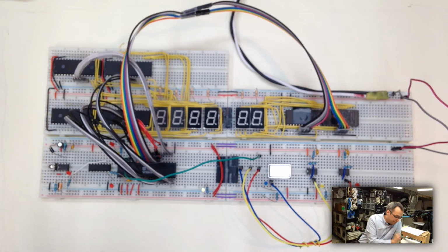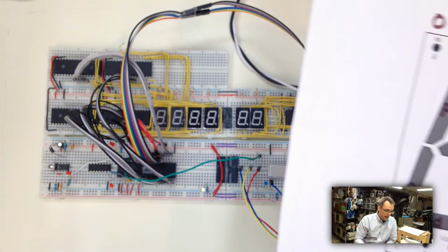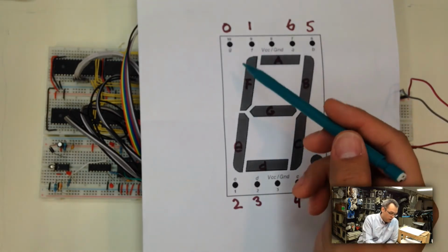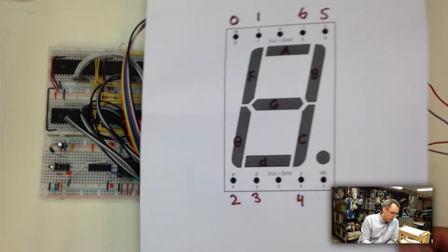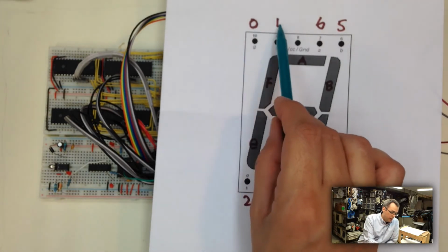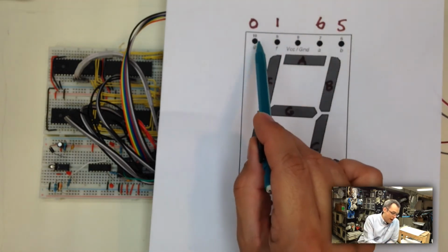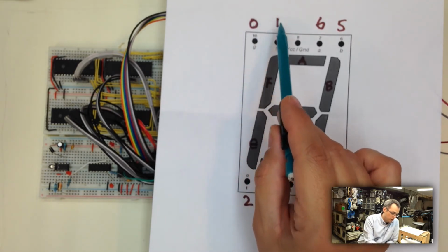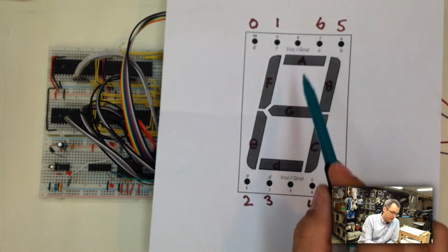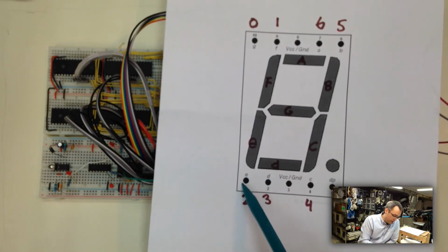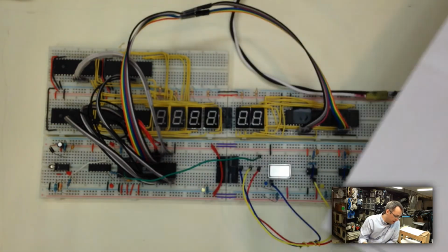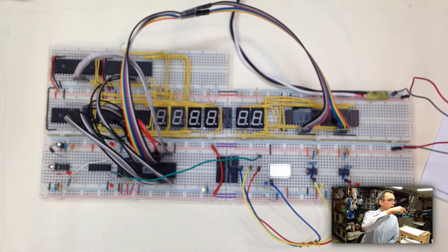And basically what I did, to get this working, is I mapped the common A, B, C, D, E, F, and G names for the pins on these guys to specific pins on my ROMs. So I mapped this to pin 0 on the ROM, and that to pin 1, and to 2, and to 3, and to 4, and 5, 6. I don't remember exactly why I did it in this order. It probably had something to do with ease of wiring when I was breadboarding it. But basically, like this guy here, for example, pin 1 or pin E on this connects to pin 2 of a specific ROM there.